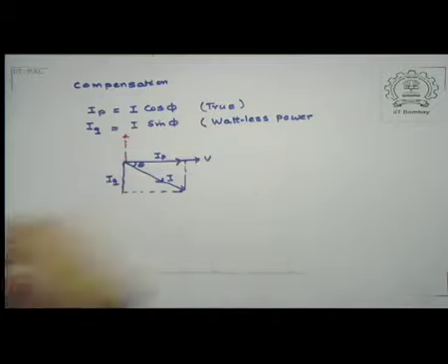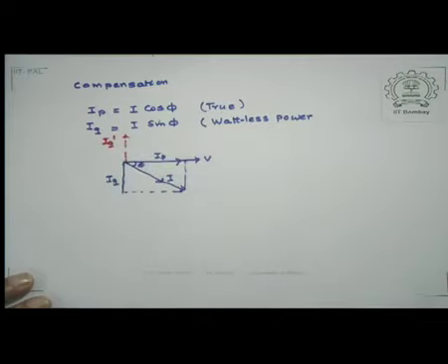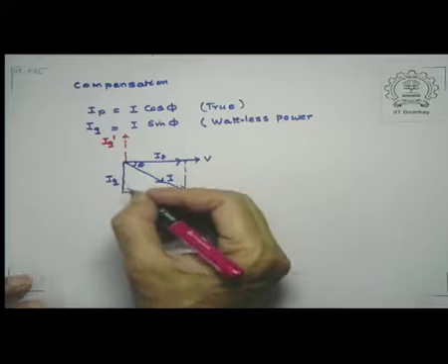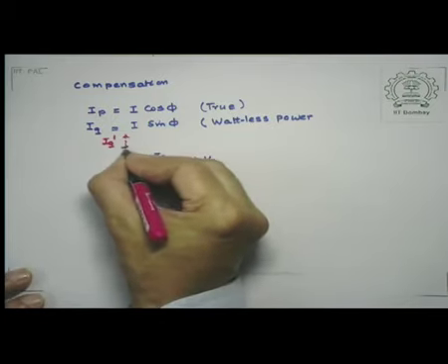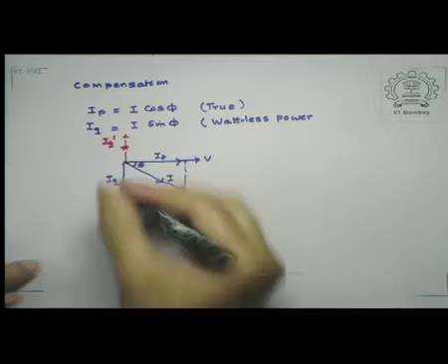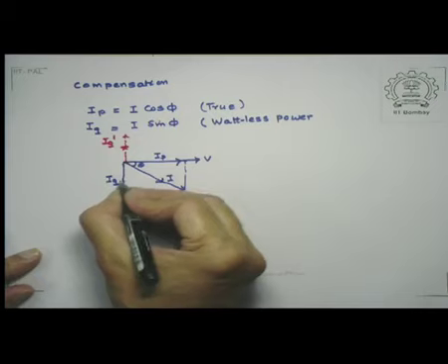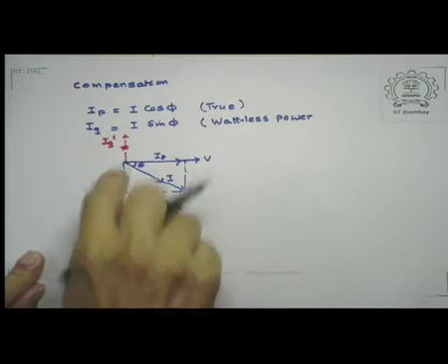So this is what ideally we would like to do. I want this to be IQ, let's call it IQ prime. Now in practice, a complete cancellation is never possible. So what we do is provide a capacitive element which will not completely compensate it, but maybe compensate up to this distance. As a result, because this much of the capacitive component has cancelled here, the triangle has come up to this point now, which is your IQ minus IQ prime.